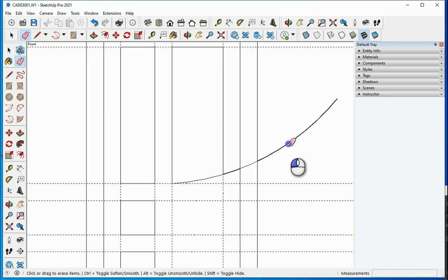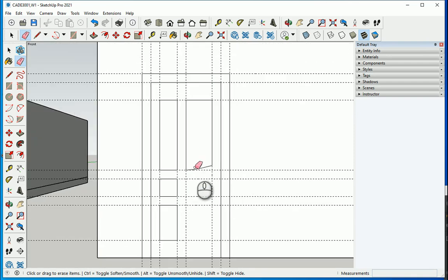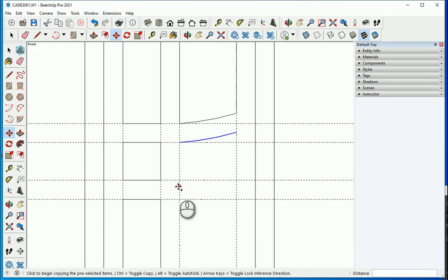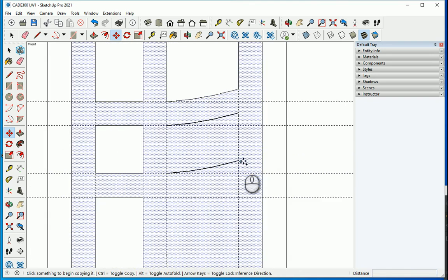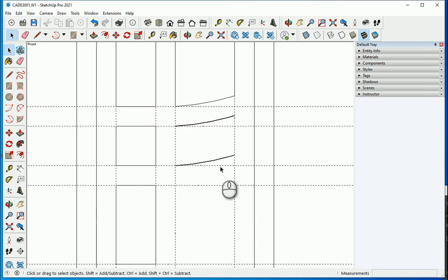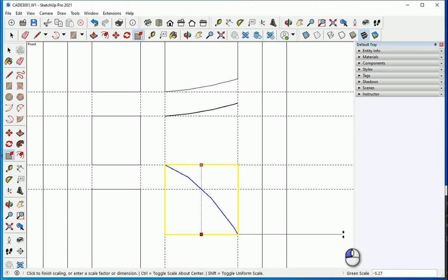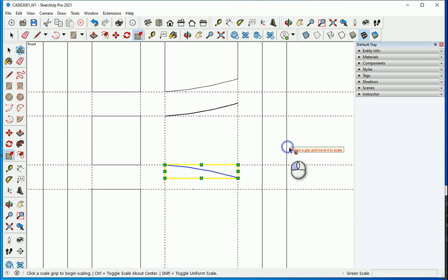and then of course you can use the eraser for this. Now I want to select this line, move and copy that, hold Control to switch between move and copy, copy it here once, and I also want to copy that here once, right? So this one is going to be mirrored. In order to mirror it, select it, and we're going to use the scale tool. The shortcut is S, right? When you grab this box at the bottom and move it down, when it says -1, it means that it's now mirrored. So this is how you can mirror.